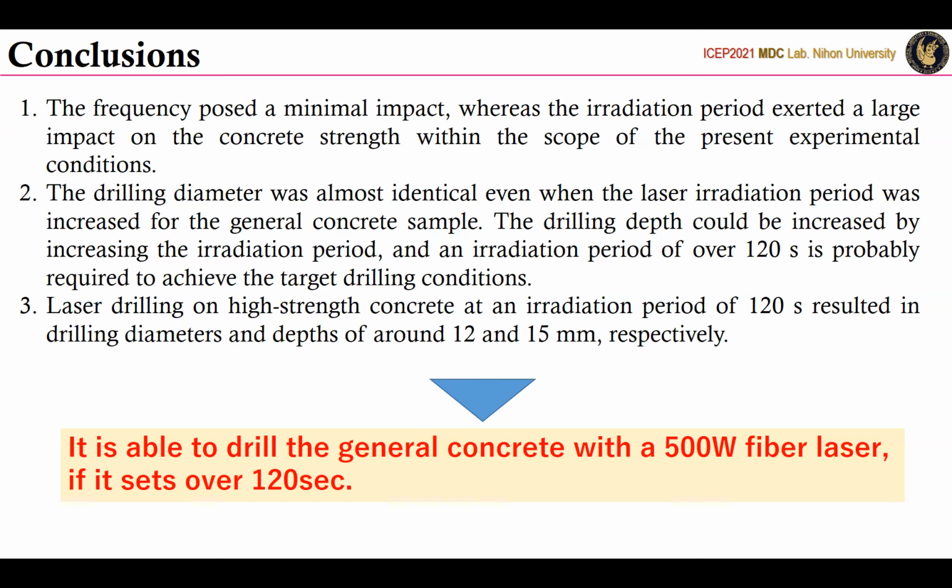What do these results tell us? It's able to drill the general concrete with a 500-watt fiber laser if it sets over 120 seconds. This is an important point.